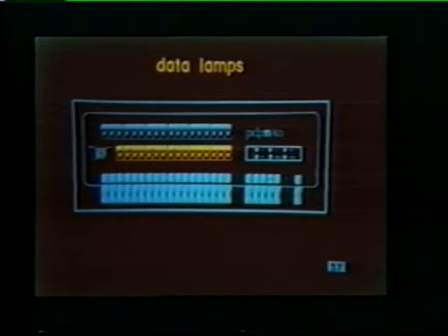The address lights relate directly to the SR switches underneath them. A color-coded bar above the lights makes it easier to translate the light configuration into an octal number. Note that the color coding matches that used for the SR switches. The 16 data lamps are located immediately below the address indicators. Only 16 data lights are provided, since no PDP-11 data word can exceed 16 bits. Again, there's a direct bit relationship with the SR switches. The color-coded bar above the lamps serves the same purpose it did for the address lamps, to aid the operator in reading the octal equivalent correctly.